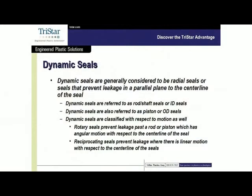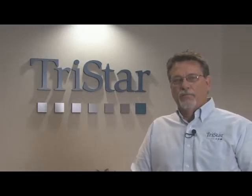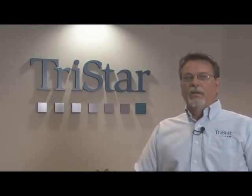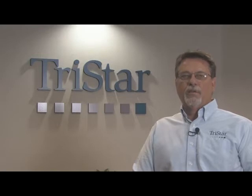Dynamic seals are considered to be radial seals, or seals that prevent leakage in a parallel plane to the center line of the seal. Dynamic seals are typically going to be either rod or shaft seals or a piston seal. And those seals can be further classified as rotary, oscillating, or linear. You can have rotary rod seals, which is usually referred to as a shaft seal. You can, in some cases, have a rotary piston seal. More often it's a reciprocating seal. And then there are some situations where you can have oscillation as well.